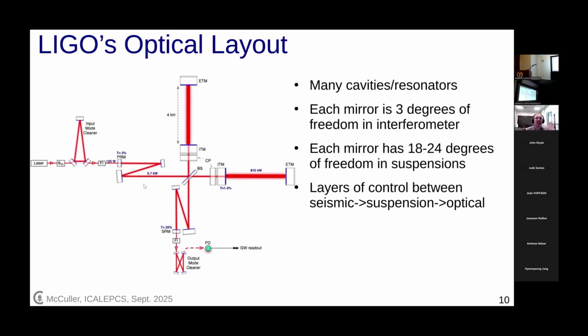So we use a giant hierarchical and distributed control system to do this, which looks very much like the one we just saw: it uses EPICS as a stack, CPU control with all of the state, and cascaded biquad sections to do most of what we do. And we just use classical controls for all of the design.